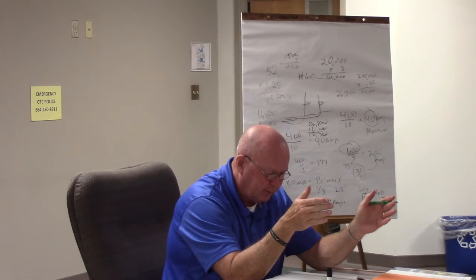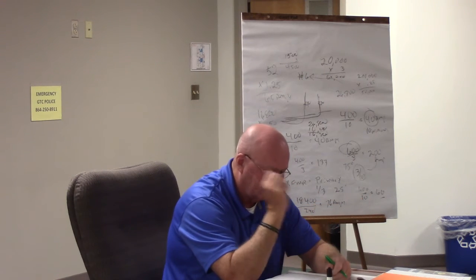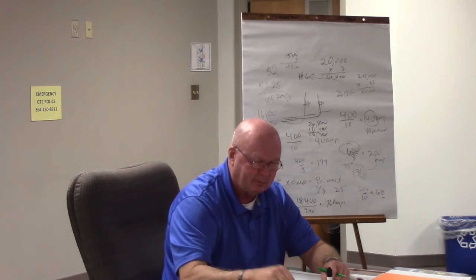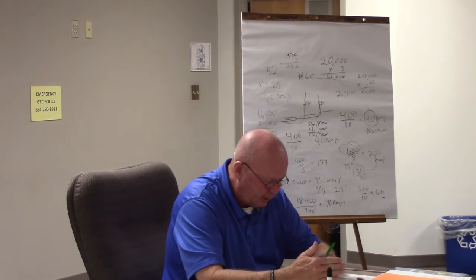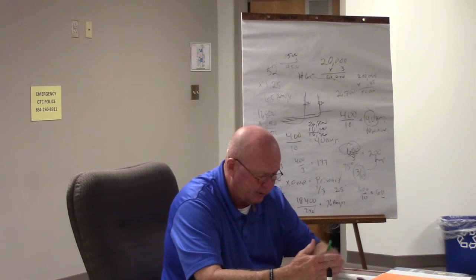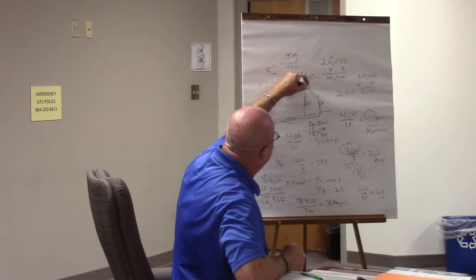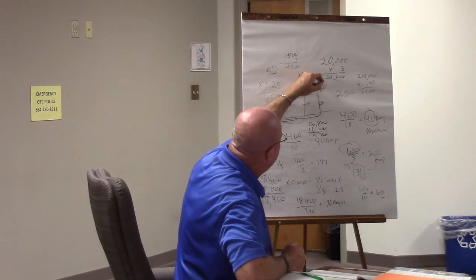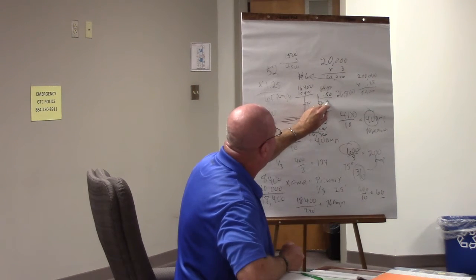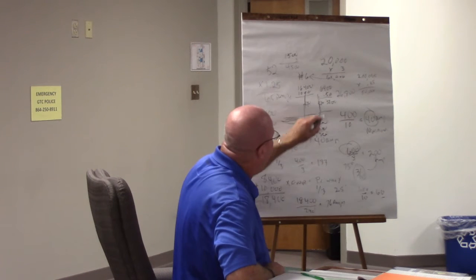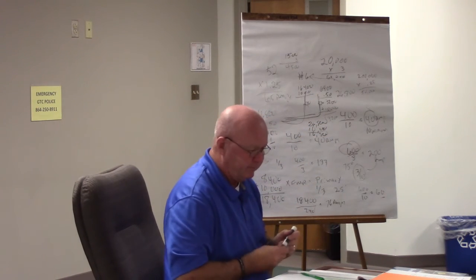The total general purpose receptacle load in an office building is 16,400 VA. The demand load is what? Let's go back to our table. When we did an office building, we took 10,000 out at 100%. So we take the difference. 16,400 less 10,000 is 6,400. And what percentage are we going to take of that? Half of it, multiply times 0.5. We get 3,200. Add it back to 10,000, and we get 13,200, and hopefully that's one of our answers. C. All right, next week.